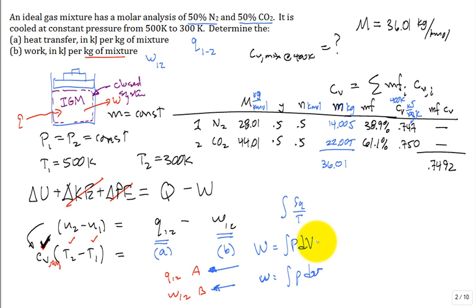So it's a constant pressure process, so this just goes to P times V final minus V initial, true or false? And I can write this as P2 V2 minus P1 V1. So we can at times get the work from first principles because it's the integral F dx, which in thermodynamics is boundary work, integral P dV. And it's especially helpful when we have a constant pressure process.